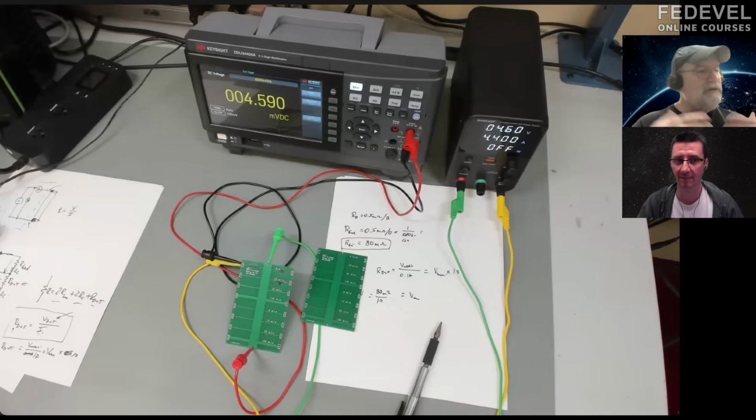The resistance, you can calculate what it is. Rarely will that be an issue in signal lines. And when it is, okay, you use a wider line. But unless you have a strong, compelling reason otherwise, signal lines you want to route with as narrow a trace as you can for higher interconnect density and easier routing. And for power traces, unless you have a strong compelling reason otherwise, 20 mils wide is a good line width to use. And again, that compelling reason is when you put in the numbers and the resistance is too much.